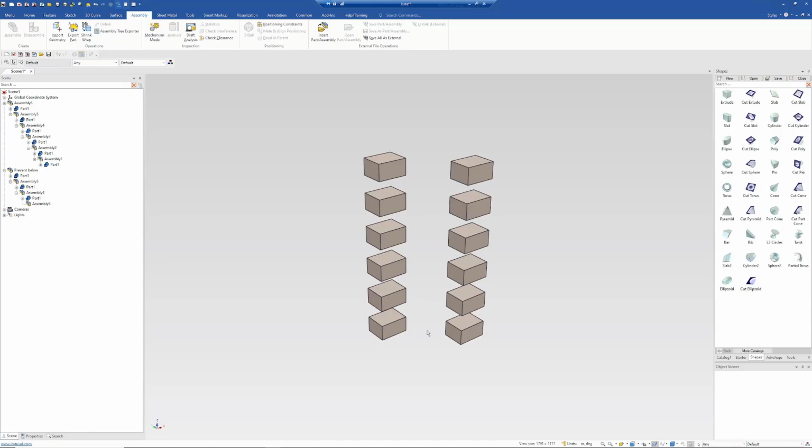However, using the tilde key and click, you can go down to the lowest possible assembly for our first assembly, and then when you select it for our prevent below assembly, it will only select up until the lowest possible, which in this case is assembly 3. Using this command and the tilde click command will select the lowest possible assembly in your tree and not go any further. However, using the Control click command will always go down to the lowest part setting.